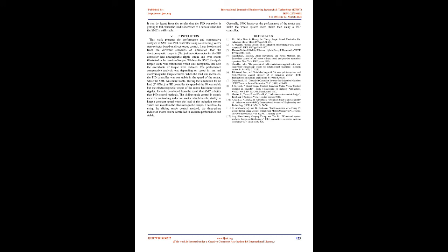Conclusion. This work presents the performance and comparative analyses of SMC and PID controllers used as a switching vector state selector based on direct torque control. It can be observed from the different simulation scenarios that the electromagnetic torque in N.m of the induction motor for the PID controller had unacceptable ripple torque and overshoots illustrated in the results of torque. While for SMC, the ripple torque value was minimized, which was acceptable, and also the overshoots of torque were reduced. The performance comparative analysis was based on speed in RPM and electromagnetic torque control.